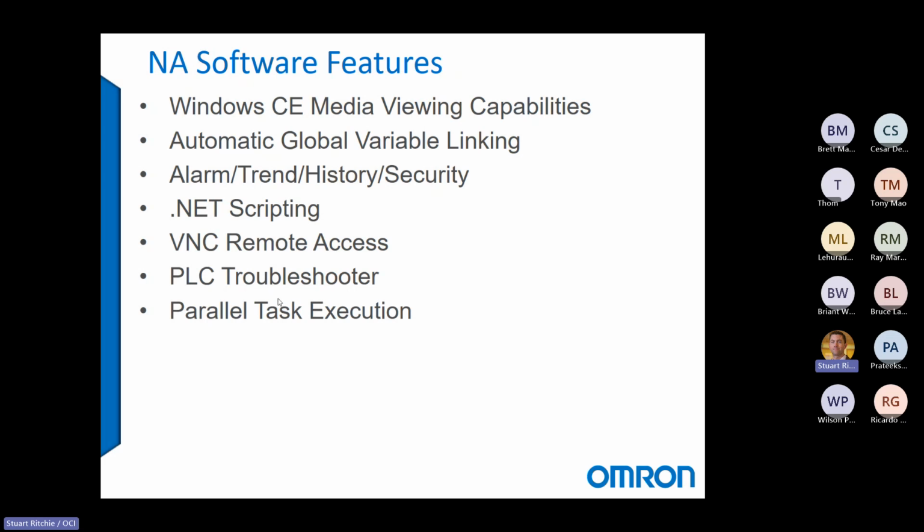So if somebody calls you up and they say, we've got the blinking red light on the PLC, what's going on? You could actually get them to open up the PLC troubleshooter and they'll have the exact same interface that you would with Sysmac Studio. So could save you a trip to site. It is optional. If you like those trips to site, when I was an integrator, I sure did.